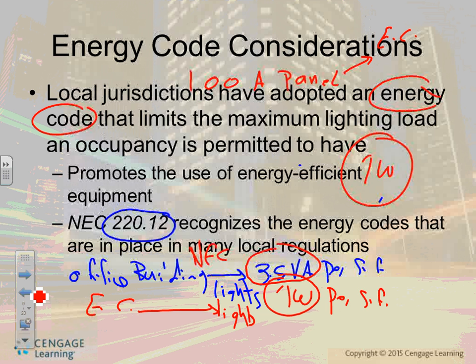If you go based on the NEC code, multiply this number by 3.5, gentlemen. What would that give you? 350 amp panel. That's your NEC code. Do you see the difference in terms of pipe and wire and conduit and so forth? For the same load, it's a 350 amp panel versus a 100 amp panel if I use the energy code. Substantially less, 3.5 times less.